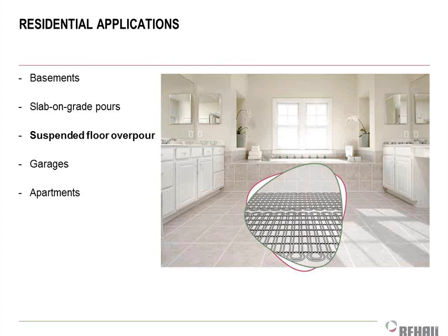So we do want to put some sort of insulation below the radiant tubing. Now, the ground itself is a fantastic insulator, so it's not like the outside of my building where I'm giving up heat to the outdoors and it's 0 degrees. Below my building, my ground temperature is probably in the 50s or 60s, so I'm not giving up a ton of heat, but I still don't want heat going down, right? So I'm going to put some kind of insulation under there. The two most common types are foam insulation, and some of the manufacturers make these foam panels you lay down that have these, what I'm going to call, I wish I had a picture, I should have put a picture on here.